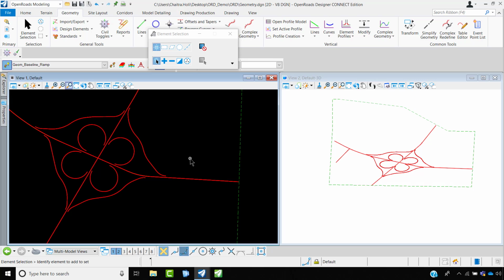Or say you might be working with your AASHTO standards and you want to see whether the values that were assigned in concept station are following the standards. Then these design standards assist the designer to monitor the required curvature and other checks when performing the geometric layout. So where do you find these standards?